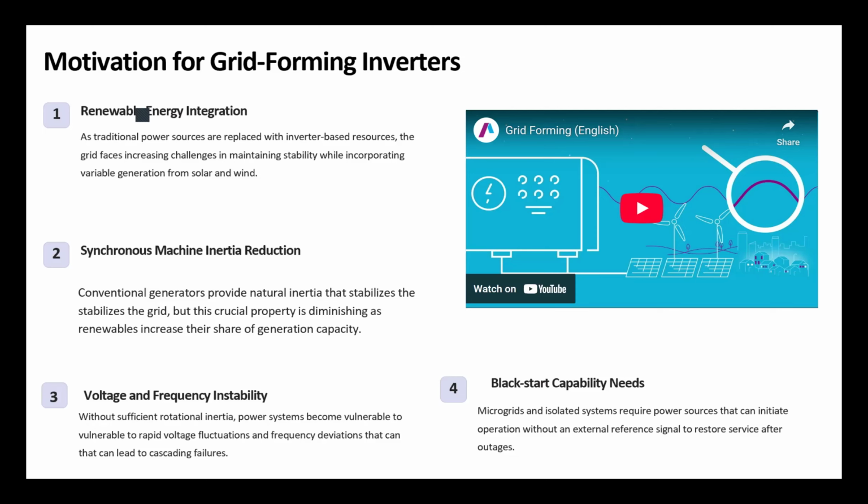This is one of the reasons. Another one is that, as you know, the control system of the inverters works very fast compared to the traditional rotary machine system. In a rotary machine, the control system would respond to the change, but in order to give that rotary machine time to transition from the previous state to the new state, there is going to be a delay.